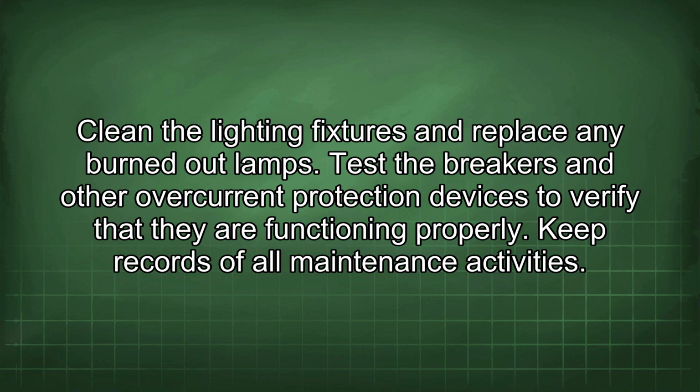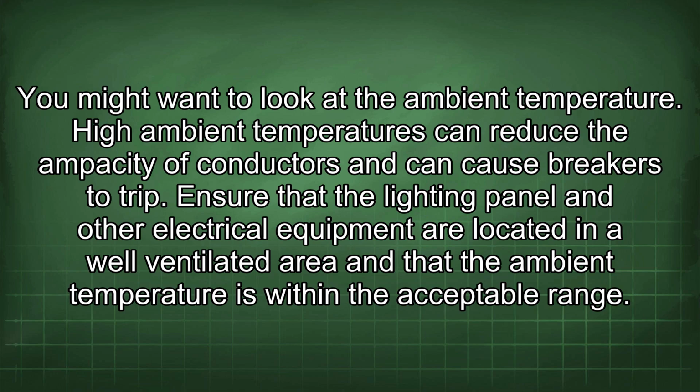Test the breakers and other overcurrent protection devices to verify that they are functioning properly. Keep records of all maintenance activities. You might want to look at the ambient temperature. High ambient temperatures can reduce the ampacity of conductors and can cause breakers to trip.